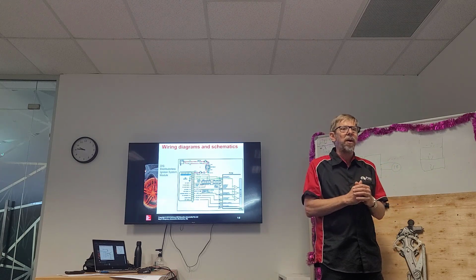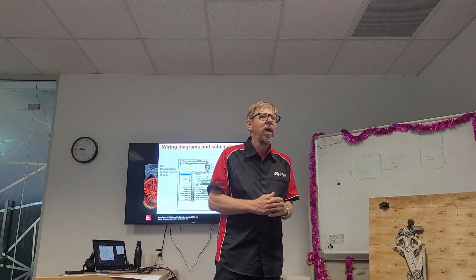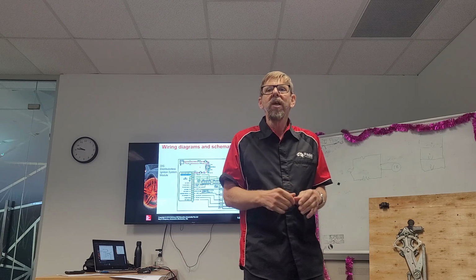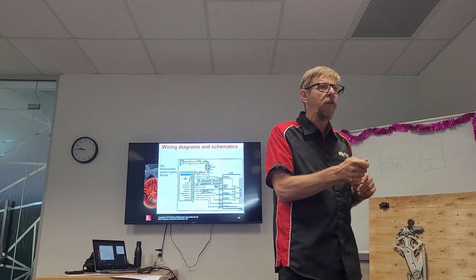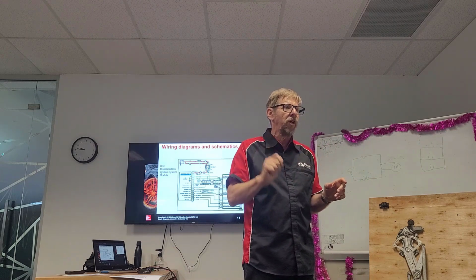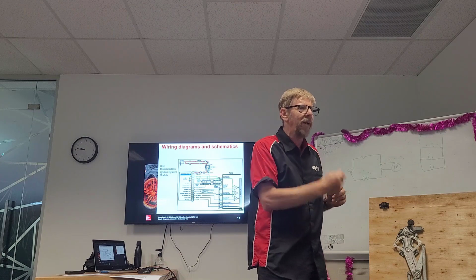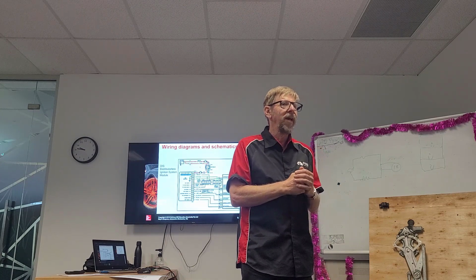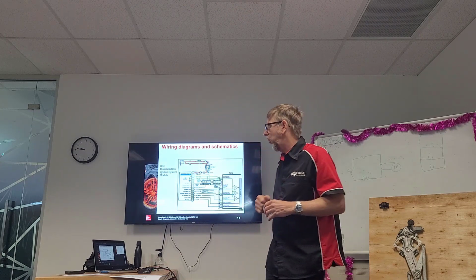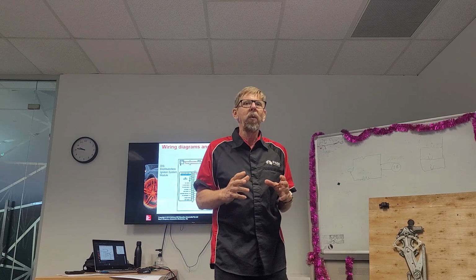I don't expect you to know everything from what I'm saying, but what Paul Denner said in his video was practice, practice, practice. Grab some wiring diagrams, start marking them out. Get used to using some highlighters so you start to see how the circuits work. Always remember, we've got a power, we have a ground, and follow the circuit, and get familiar with doing that, all right? Without a good wiring diagram, we are lost.